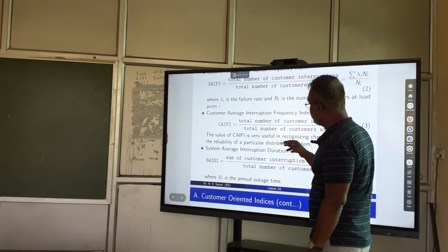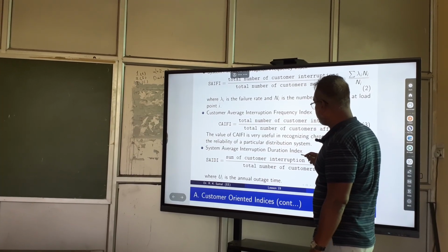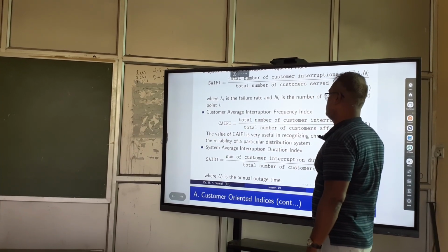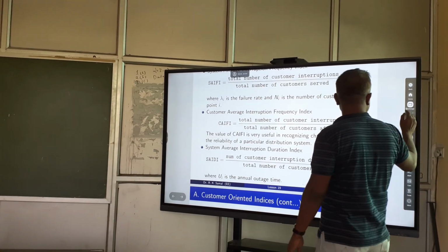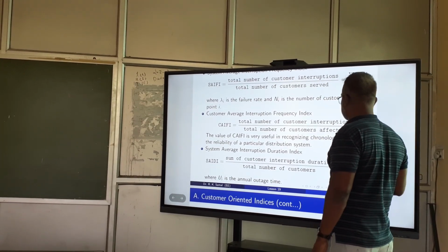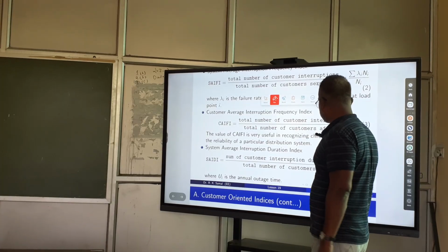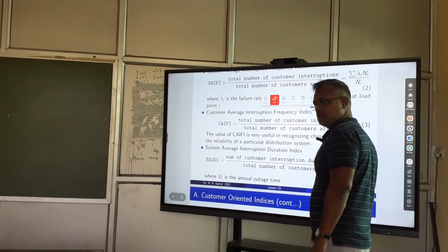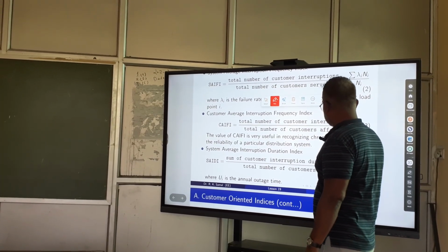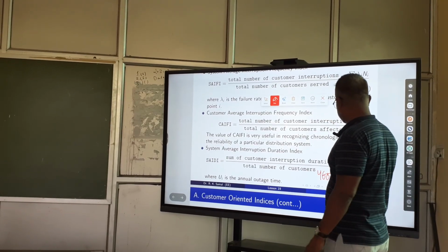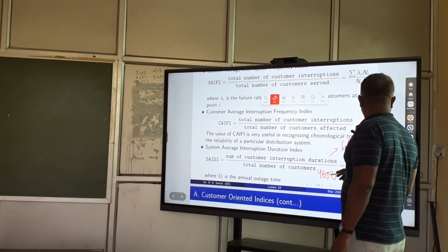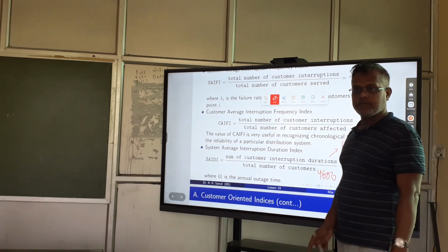SAIDI: sum of customer interruption durations divided by total number of customers. This is 4,000, and the numerator is 6600. Divided, that gives 1.65.